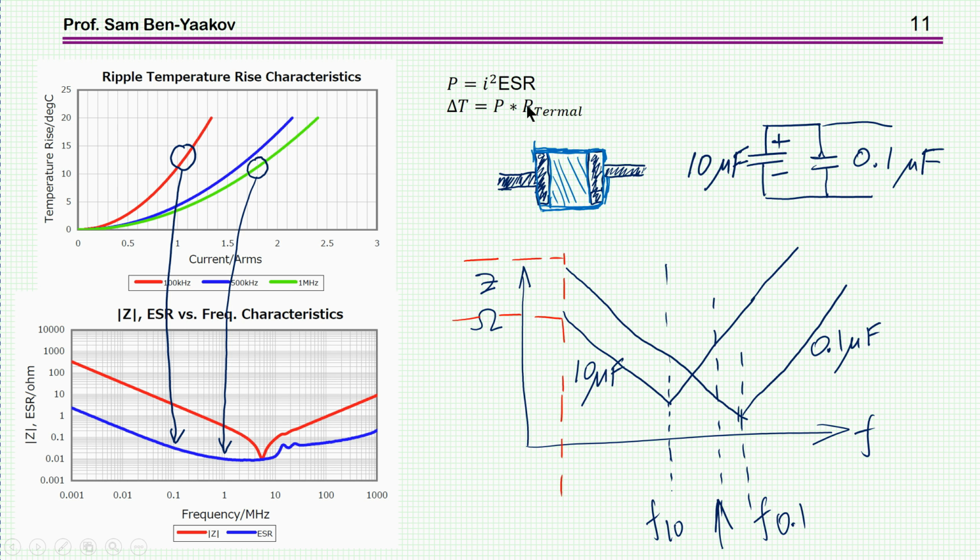And this thermal resistance is a function of the layout, actually, because these traces are acting sort of as a heatsink, and therefore this should be specified for a given layout, okay? Because if the pads would be much larger, then the power dissipation could be even better and the temperature would be lower.